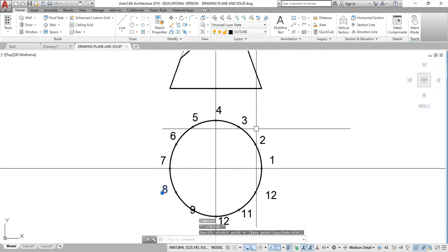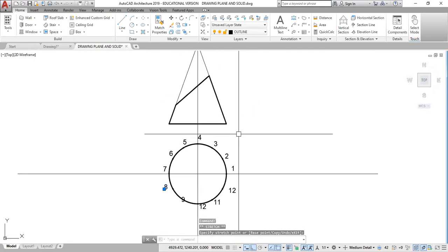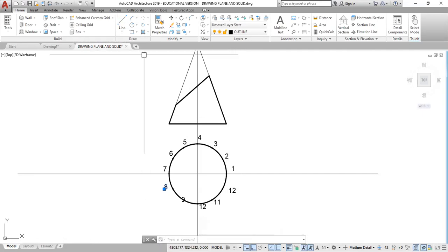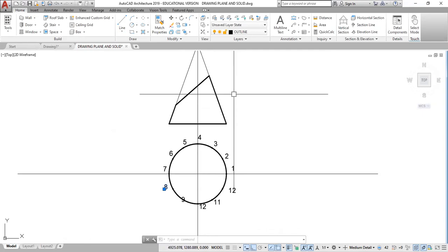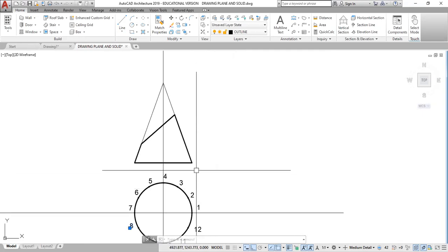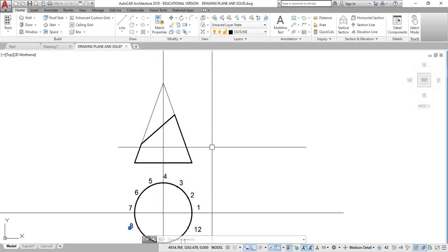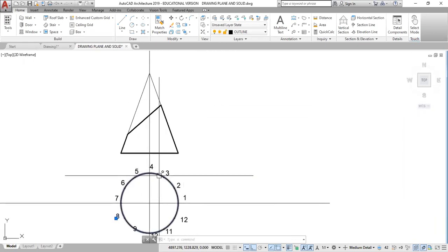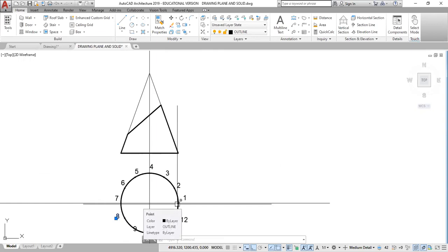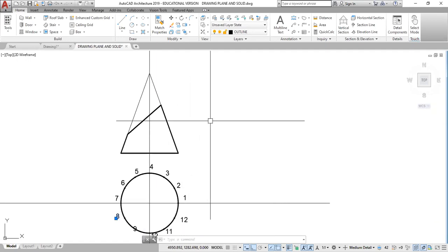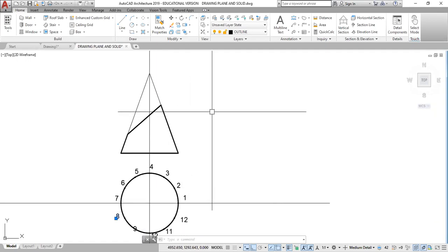The next thing is to draw lines from, well, let's do the development first. Next step is to draw an arc. We need to establish the distance or the perimeter for this circle. The perimeter for the circle is pi times, how do we find the distance around a circle? We multiply pi by the diameter. And the diameter in this case is 60. So we multiply 60 by 3.142. How much does that work out to be?